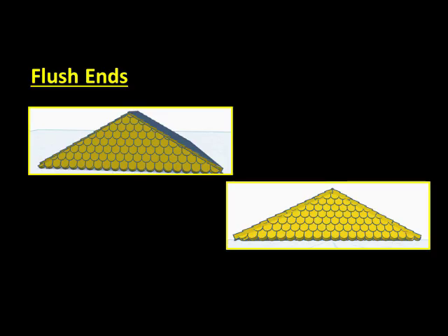One other observation. If the end caps appear to be a bit indented into the main panels, you can move them back a bit, perhaps 0.5 to 1.0 millimeters, prior to grouping to get a joint that is a bit more flush.